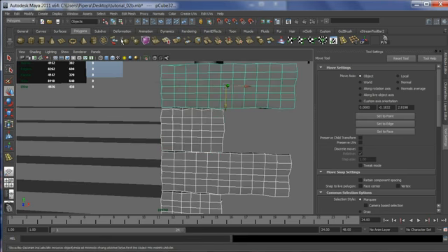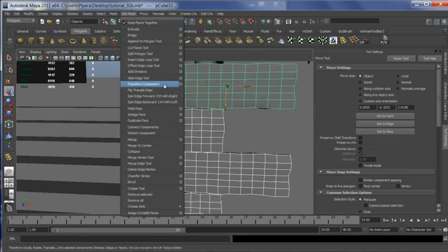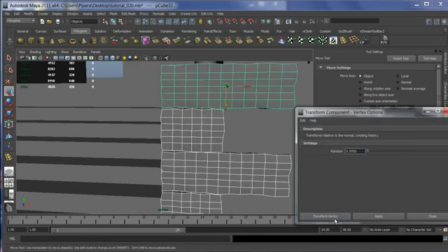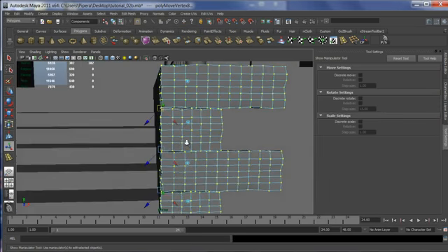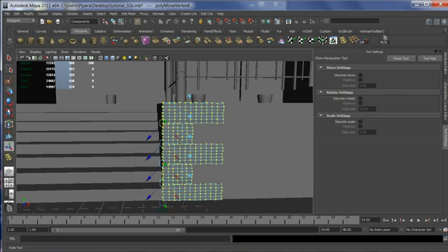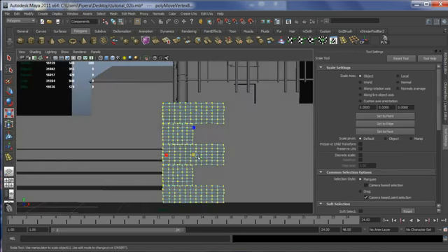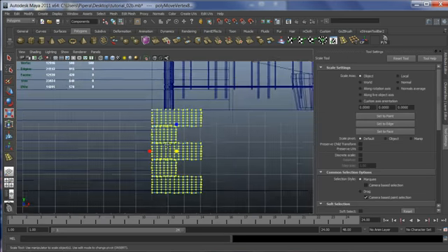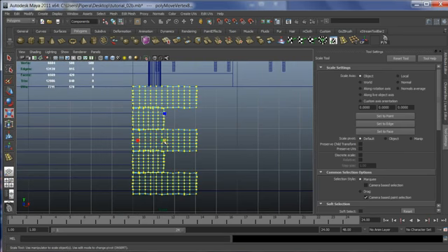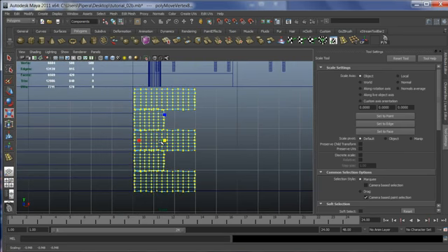So we have now 5 stones, and let's go to edit mesh, transform component again, and zero out the random transformation, and we can get the scale tool, scale all 5 of the stones equally from the center, not individually.